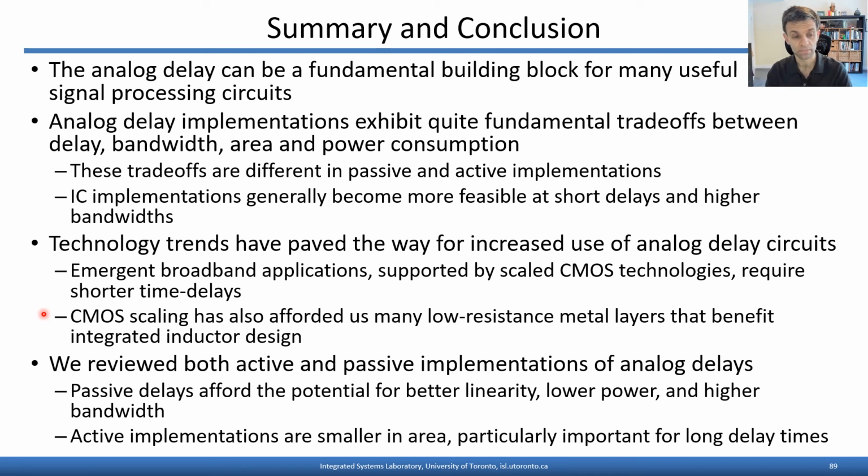At the same time, CMOS technology scaling has afforded us a lot of low resistance metal layers in the technology, and that benefits the implementation of integrated inductors, which are often playing an important role in passive delay circuits.